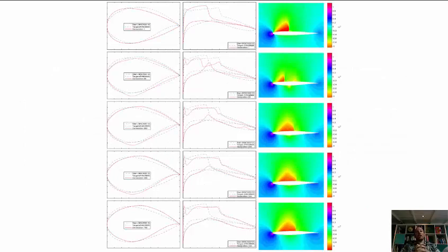Aerodynamically, the first problem that we attempted to solve was inverse design of an aerofoil shape. So in this case we started with the NACA 0012 aerofoil geometry, and we wanted to drive that shape towards a known pressure distribution, a pressure distribution that we'd already run based on an RAE aerofoil at a transonic Mach number where you've got a standing shock wave on the surface. Aerodynamically a very sensitive problem. The aerodynamic response of that aerofoil is very sensitive to geometry movements, and we were able to show that this scheme was able to solve that problem.